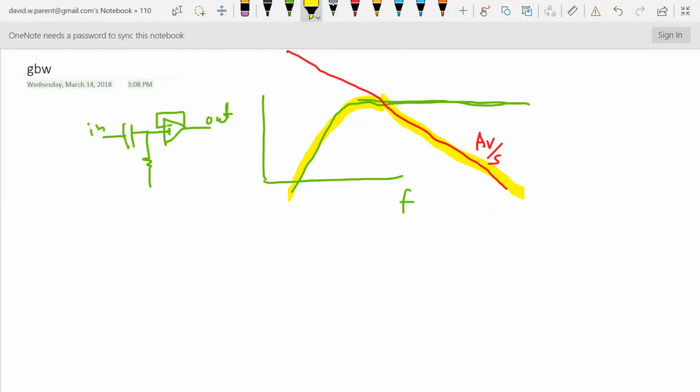But the assumption is that at this point, we still call it a high pass, because sometimes we can say it's a high pass, but the information is limited to this point in frequency. So it'll work the way we want. Now, if we had information out here that we wanted, the circuit wouldn't work, and we would have to buy a higher frequency op-amp that maybe had the gain bandwidth out here.